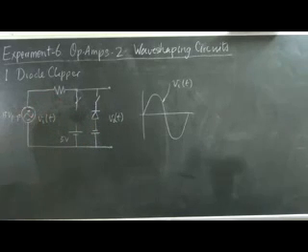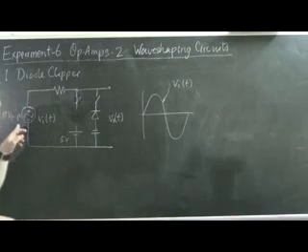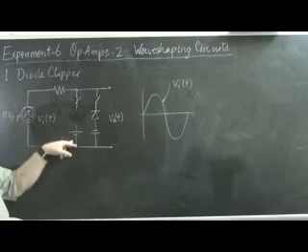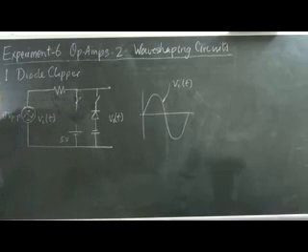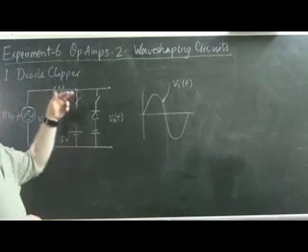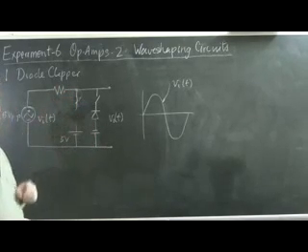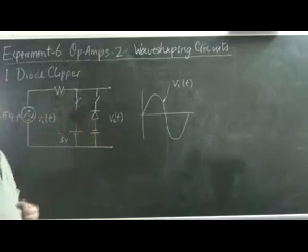This situation prevails until this voltage, the input voltage, exceeds the battery voltage. We are assuming, of course, that the diode is ideal. If the diode is not assumed to be ideal, which obviously it is not, then we add another 0.7 cut-in voltage to the battery voltage to determine the next state of the circuit.